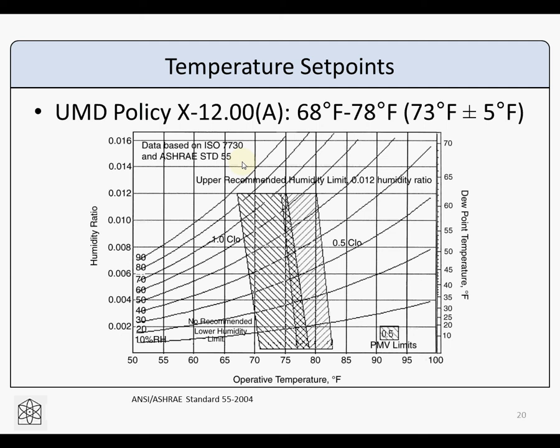If it's just in the return air, then that should be pretty simple. You figure out where the largest return air vents are, and see if you can get a measure of the temperature at that point, and that should give you a rough idea of what the temperature is. If you want, you can try to capture that over time and maybe get a better assumption there. And we have some tools in our lab to do that, just some quick data loggers, which you're welcome to use. So stop by and we can give you one of those and you can check it for your building.